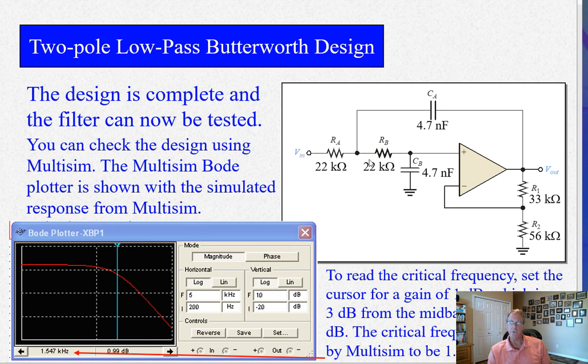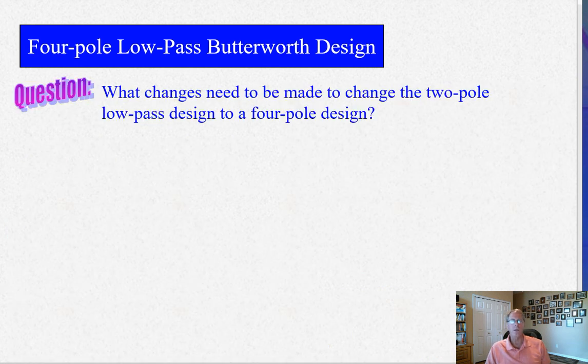Additionally, you have the input impedance of the op-amp that is high, although you probably have something in the 40 or 50K region because of these two resistors here. But that's okay, that's real high, okay? All right, so next week we're going to go on to do other filters. We're going to do a high pass filter and perhaps look at some others. So if you have any questions, please post them into the discussion.